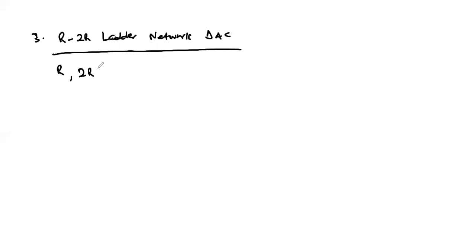The bits are weighted by providing paths for current division with consequent successive attenuation of bits of lower significance. And then the operational amplifier is also used to sum the current contributions of each of the individual bits. An example of a 4-bit R2R ladder network is as shown below.